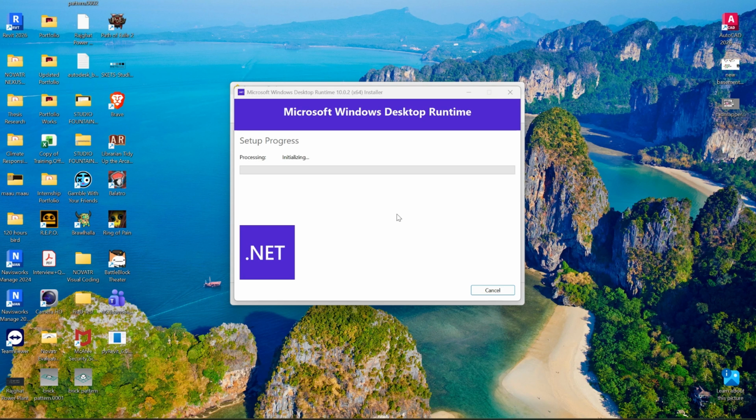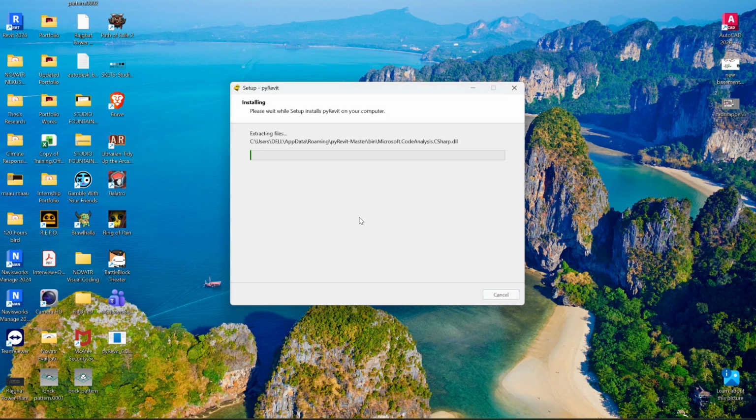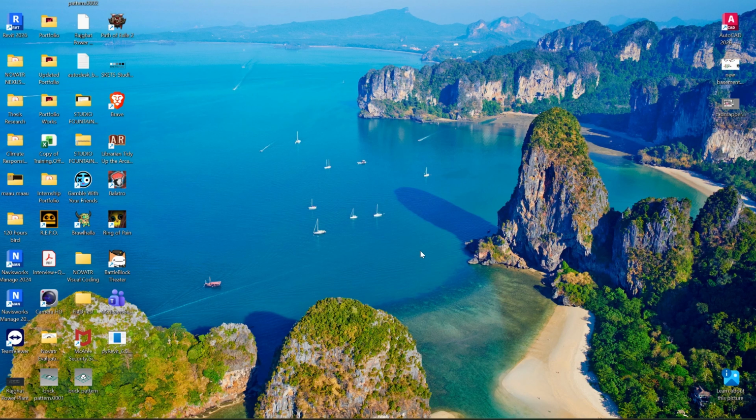The reason we're installing pyRevit is because it has a specific feature where we can use the lines that we draw inside of Revit as the hatch patterns that we need, and we don't need to convert them into some other version or some other .pat file. So it's pretty simple, and it comes out as a fill region, or it can even come out as something that you can put on the materials as well. So I think it is done.